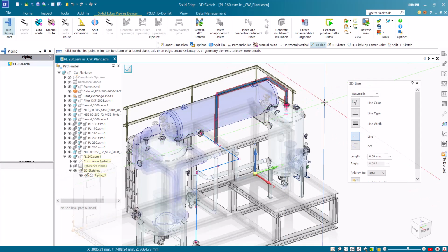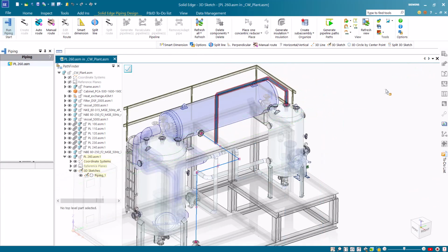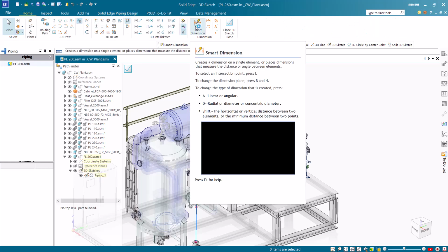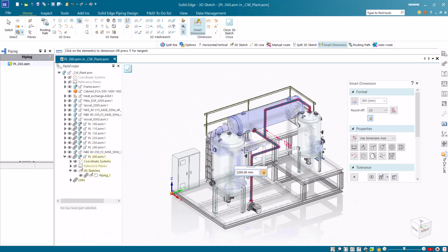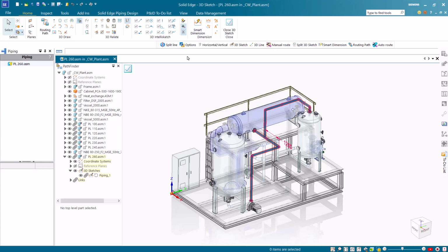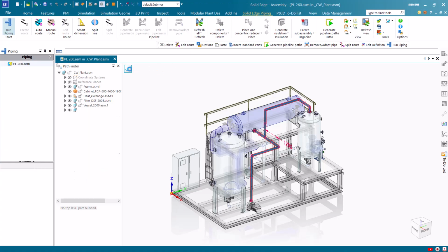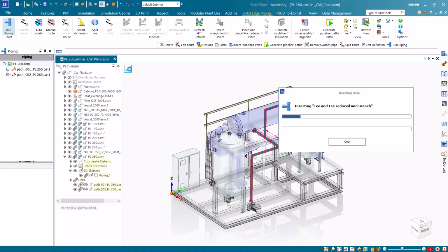As we come out of the environment, based on the pipe diameter and fittings information from the pipe spec, the piping assembly gets created. This keeps the guesswork out and piping assembly is created with fittings as per the standards registered in the pipe specification.